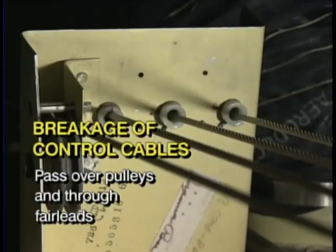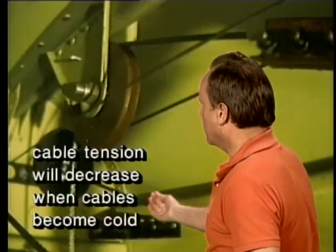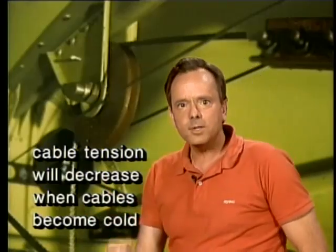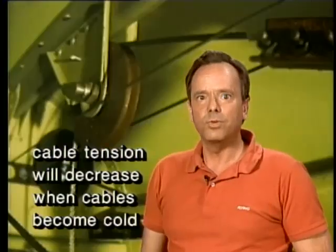All right, now the next thing we want to talk about is in a cable-operated control system of an all-metal aircraft, and it does not incorporate a temperature compensating device, and it's been rigged to the correct tension in a heated hangar. Now, if the aircraft is operated in very cold weather, they're going to ask you what will happen to cable tension in cold weather. Well, in very cold weather, cable tension will decrease when the cables become cold. And the reason for that is the aircraft actually shrinks more than the cables do, so cable tension will decrease when the aircraft structure and cables become cold. It's both of the two combined that become cold.